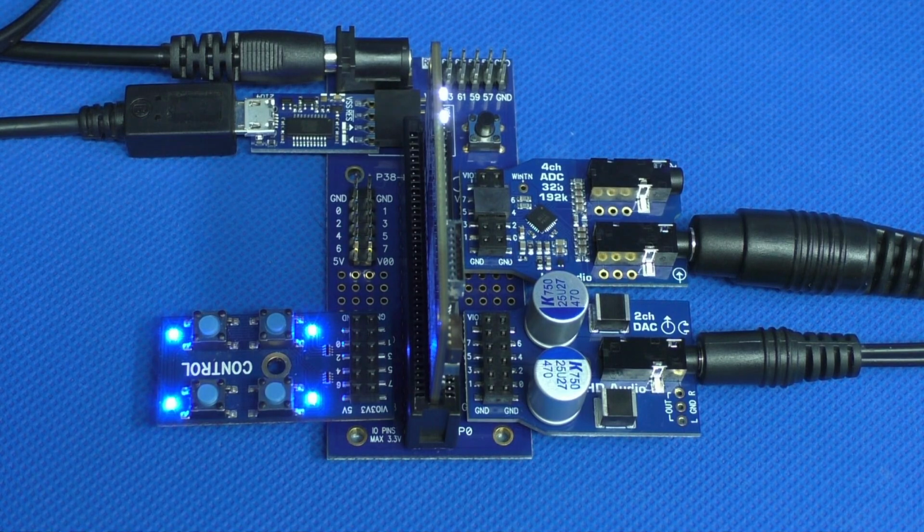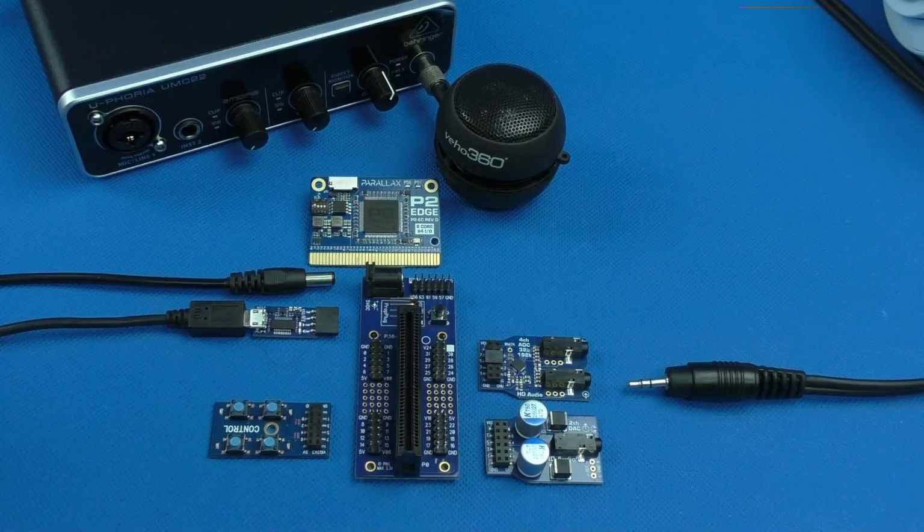But you can configure it in code to work with digital microphones or our old school analog microphones, and you can apply a phantom power pull up to it. And that's also configurable on both left and right channels simultaneously, or just the left or just the right. So you could use two different mono microphones plugged into that top jack and configure them differently. And so quite versatile.